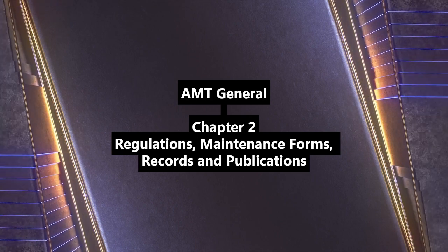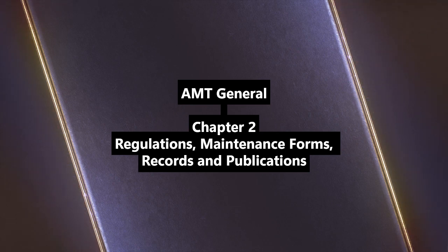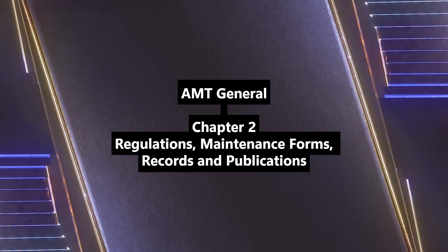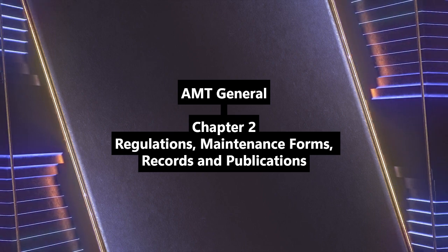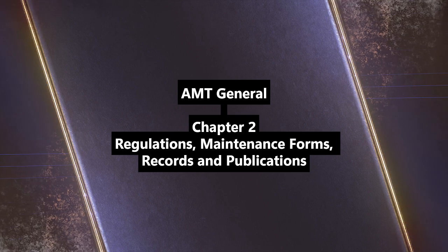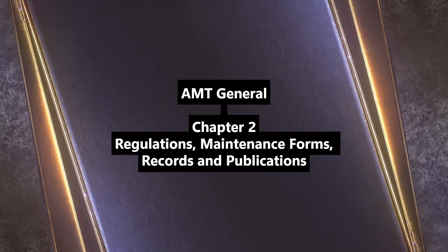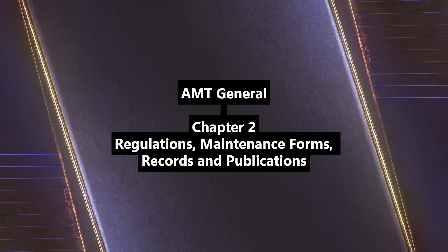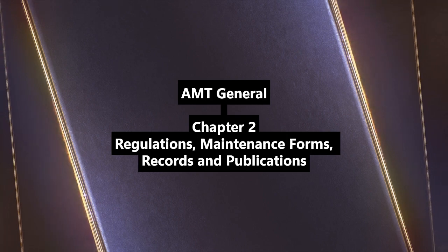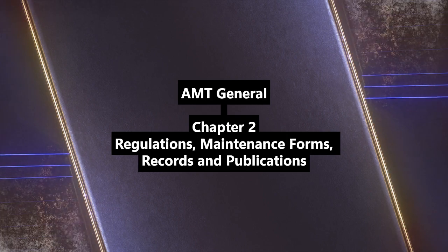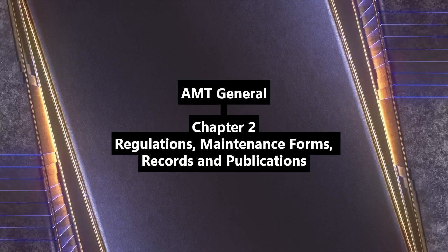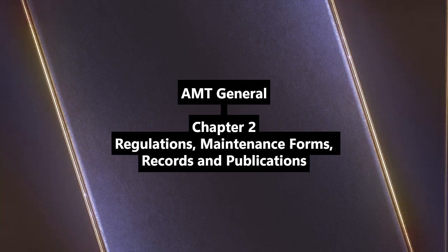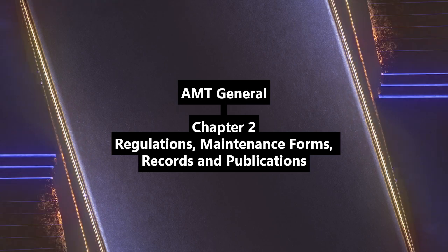It really does. And at the very heart of all this is the definition of airworthy. Which isn't just a casual term. It has a very specific legal meaning. Absolutely. And it's relatively recent that the FAA formally defined it in 14 CFR Part 3, Section 3.5. Okay, so what's the official definition? Airworthy means the aircraft conforms to its type design and is in a condition for safe operation. Conforms to type design and safe for operation.